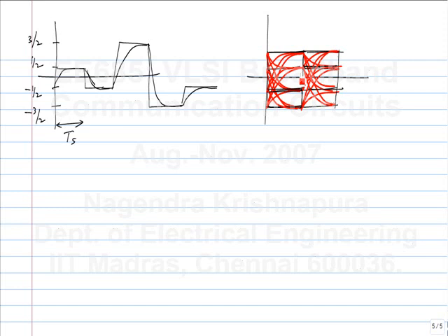So now, from the opening of each of these boxes, I can figure out, see, where will I put the thresholds for detecting data like this? Here, here, and here. So I'll always put the threshold between the two possible data values, right? So that is the opening that I'm interested in. Opening just says how far it is from the threshold, because I'm assuming that I'll put the threshold in the middle. So the opening is simply twice the distance between the threshold and each of the symbols. So this vertical opening will tell me something, and also this horizontal opening will tell me something.